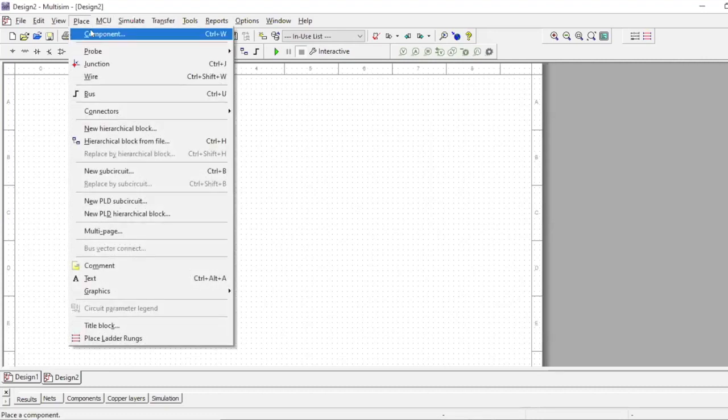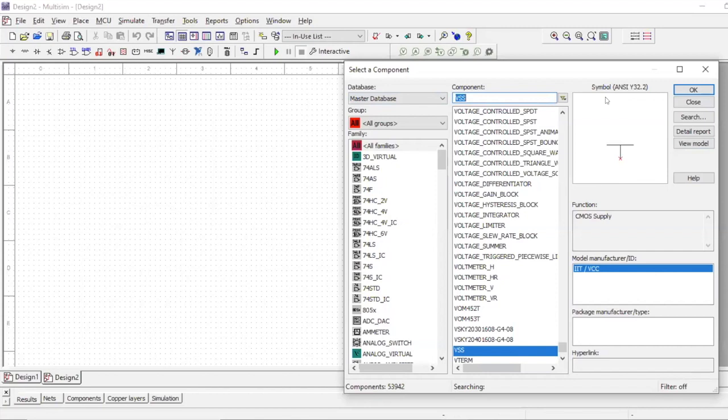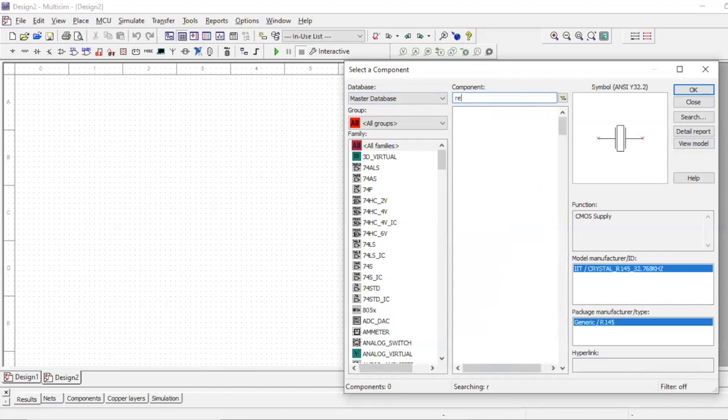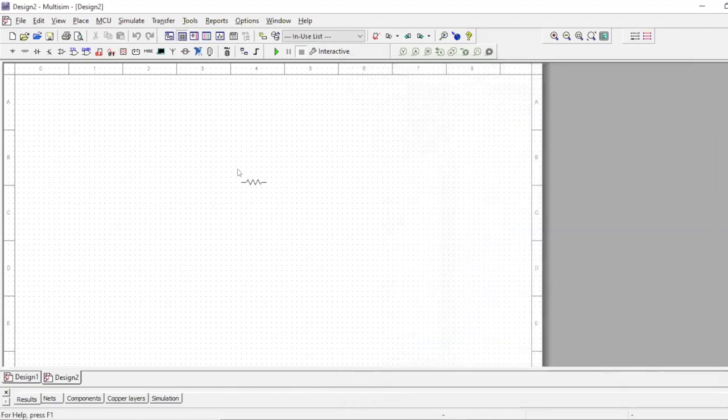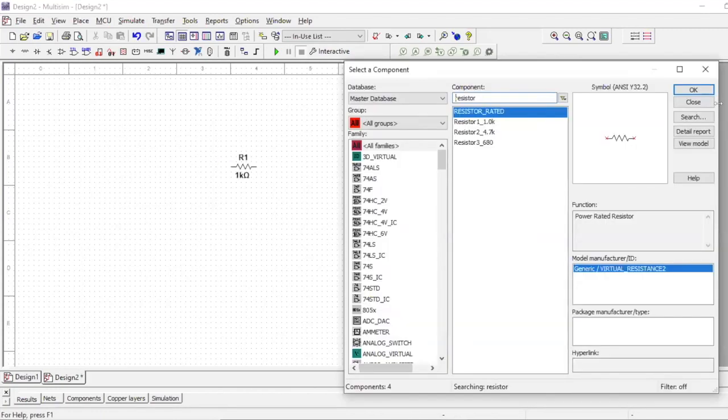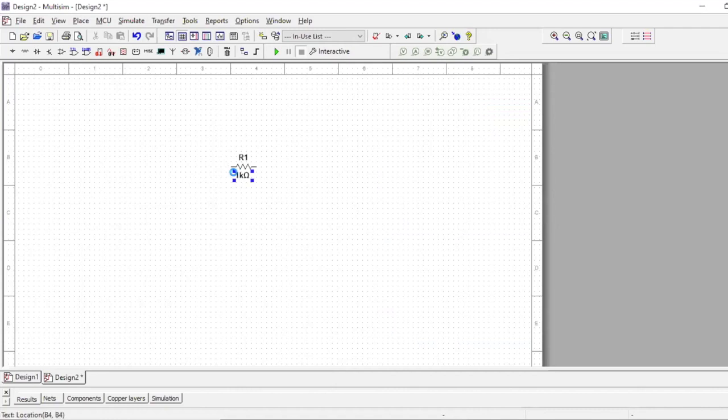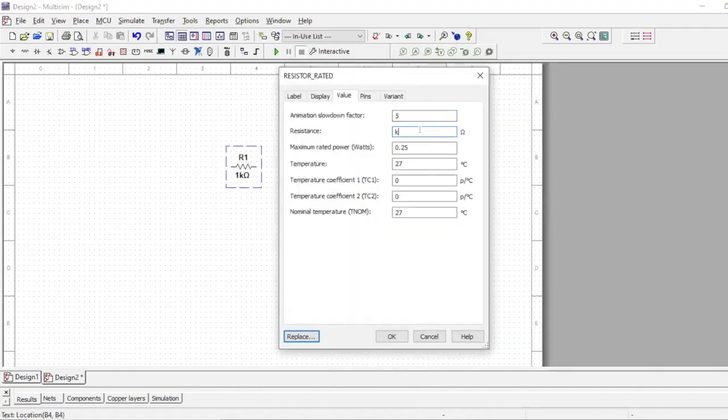When you click on place components, in my first schematic, I said that you can search the resistor when it's on all group. So when you search it up, I didn't say how to change the value when you select the resistor. You could change the value when you double click on this. Our resistor is 1M.